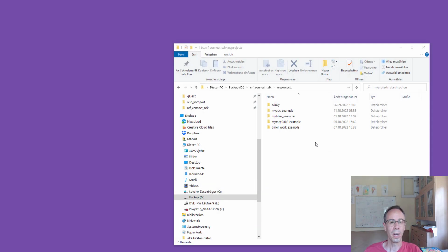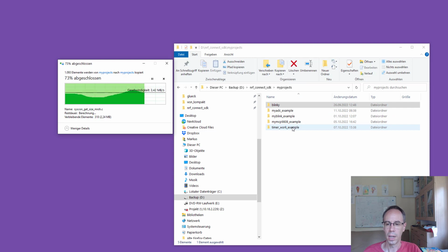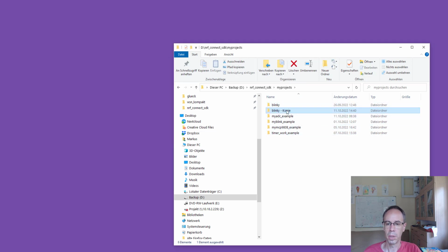To use OpenThread in Zephyr is even easier than in the nRF5 SDK before. We need for the example two developer boards, and we start again with our Blinky example. Make a copy of it and rename it my Thread CLI example, and delete like normal.